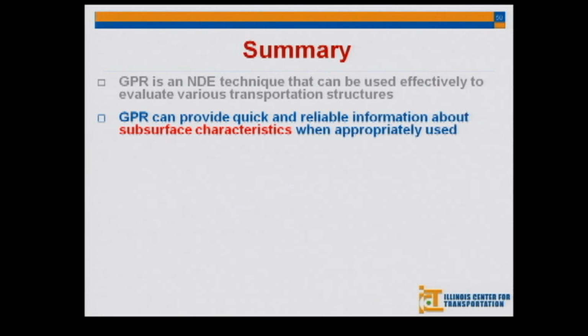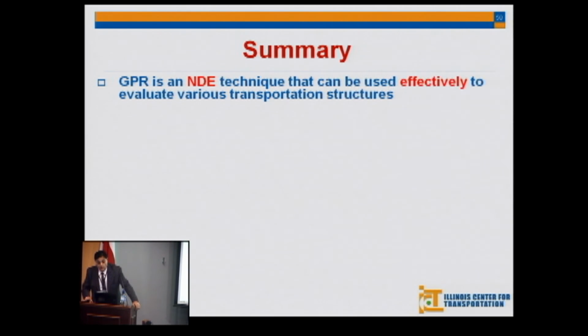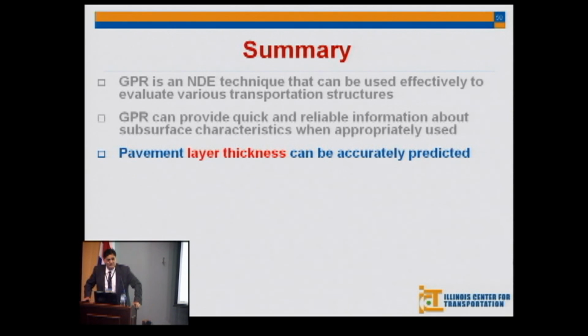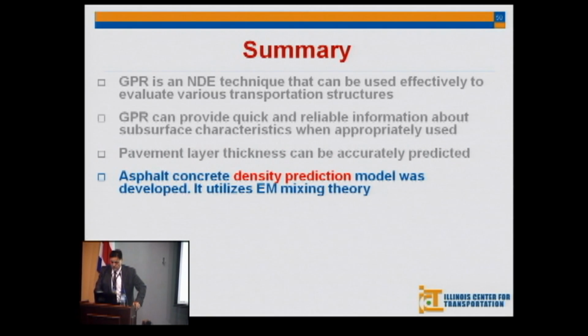So with that, let me summarize what I just talked about this morning. It's my opinion that GPR is definitely a very, very effective technique. I think it should not be oversold in some of the applications, because it is really doing a good job if we use it appropriately. It can provide quick and reliable information about the subsurface characteristics. And pavement layer thickness is not a big deal now to measure, in my opinion, if we know what dielectric constant to use.